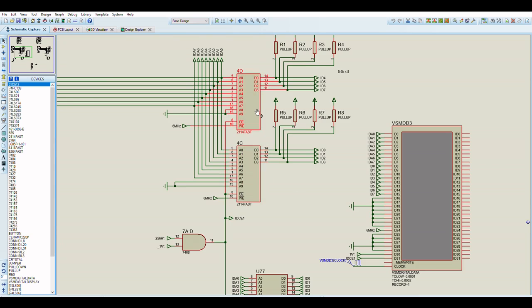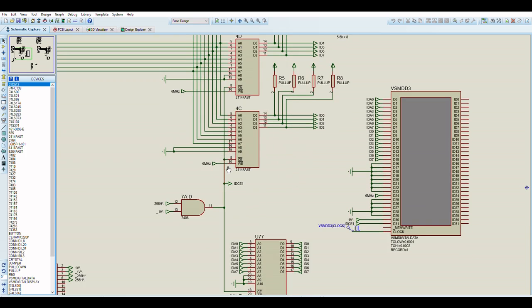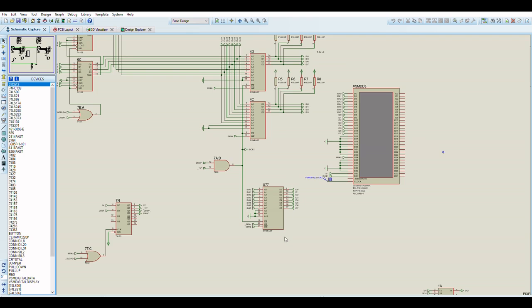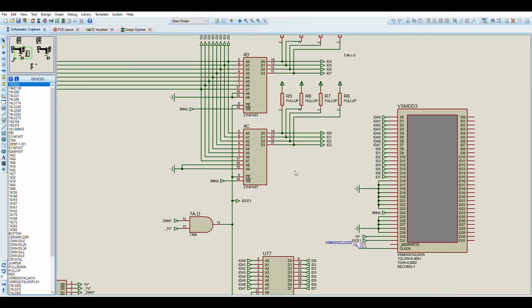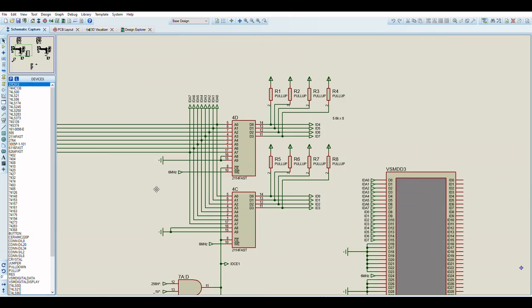So what this means is that let's assume that these RAMs, or this one, is filled with FF. The FF fill happens just after the calculated pixel data has been read from the RAM on the alternate cycle of the 6 MHz clock.